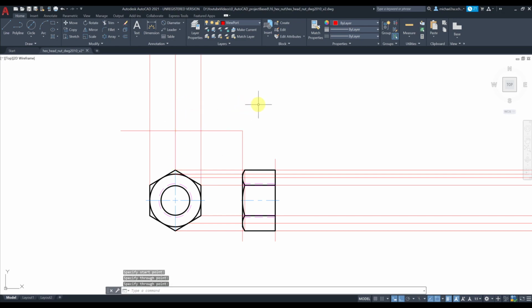And we know that to develop multi-view we're gonna need a line here of 45 degrees, so you can go ahead and just type L for line, select this point, press F8 to get out of ortho mode. I don't care about the length. With tab key you can switch to the angle, type 45, press enter. Okay, line, press enter. Let's project this point, make sure it's vertical line. Press enter, grab the intersection, and develop this horizontal line. Let's trim the extra pieces here.